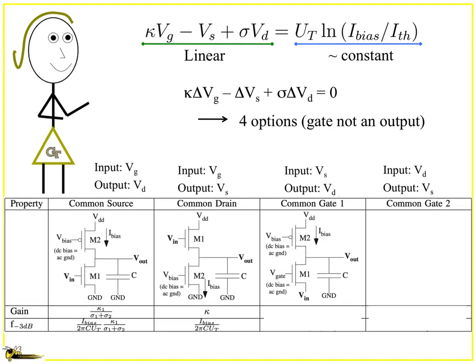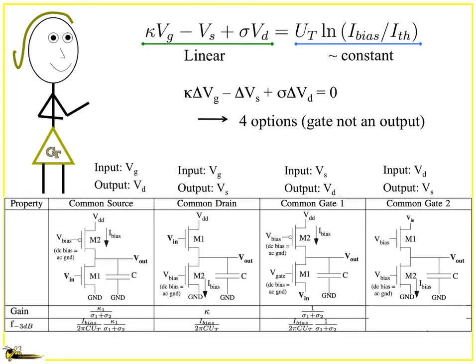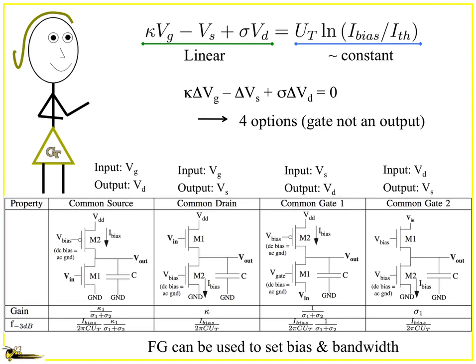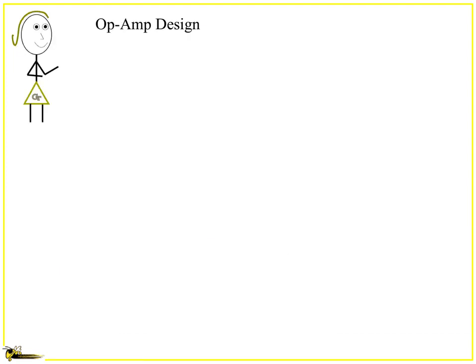And you could talk about the first common gain case, which is actually sort of a high gain amplifier case, but then you can also do the reverse case, which is often thought about for cascodes or for voltage regulators, which gives you the low gain case. And this kind of gives you a way to just abstract this whole piece out right off the bat. And this is basically what you get for one transistor circuits with current sources. And yeah, if you don't have a good current source and you have to use a resistor, okay, fine, you could do that. But this is kind of the fundamental pieces that you begin with. And floating gates get used everywhere and can set the bias and the bandwidth and all the other good parameters.